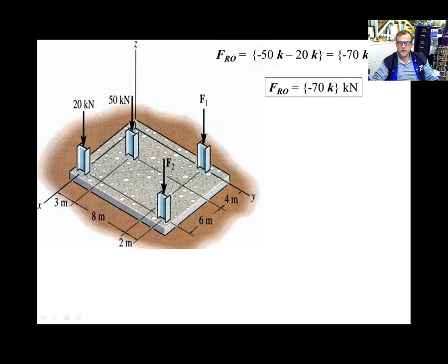How do I calculate the moment? I need the arms for that moment. So basically I'm going to have R cross F, and I'm going to do the summation of R cross F everywhere. Why R cross F? Because we're working in 3D. You can do it differently, but I don't want you to do it differently right now. So R cross F, what is it for this force? What is R? R is from here to, I know it looks slanted, I haven't told you that before, but imagine you have an ample imagination. Imagine this follows the axis, and don't make me switch it and change it.